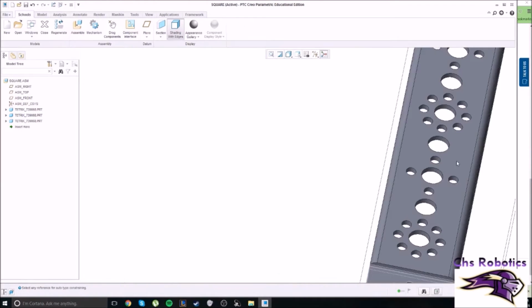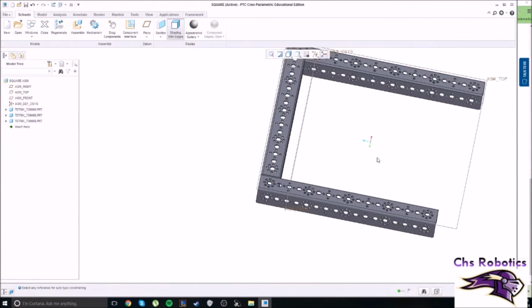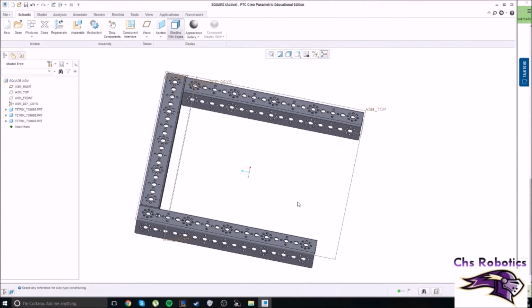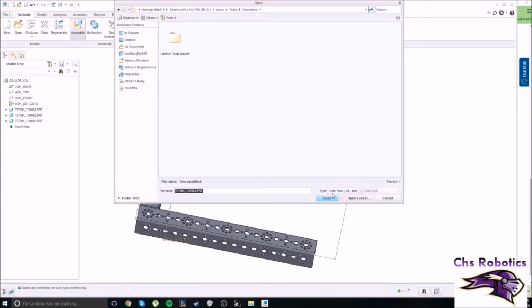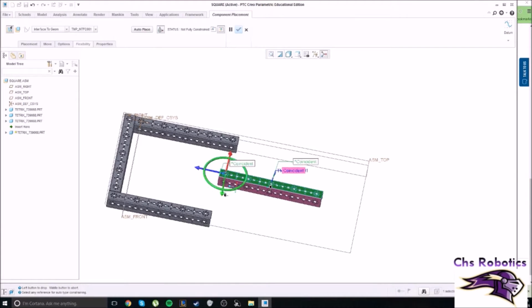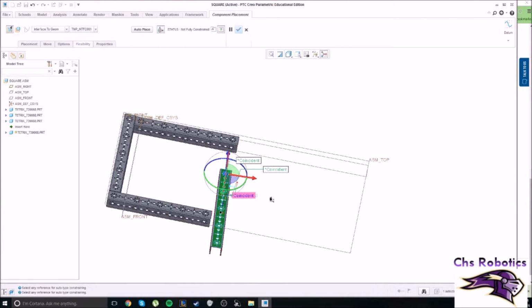Most of the time when you generate a part into PTC Creo, it's going to have the constraints that you used previously, and sometimes this can be good and sometimes this can be bad. So what you want to do here is, if you don't want to keep the same constraints after you set it down using your left mouse button, as you can see it has all these constraints already. If you don't want to use the same constraints and you want to use it for something else, you want to go into this corner right here and click on this.